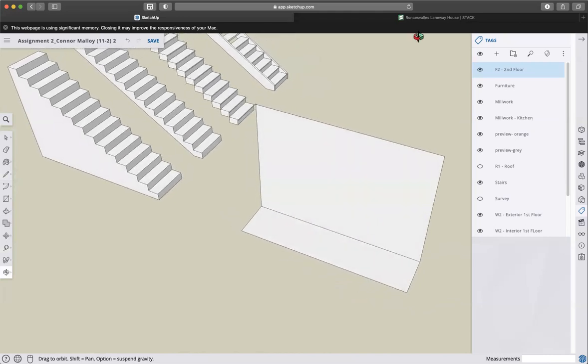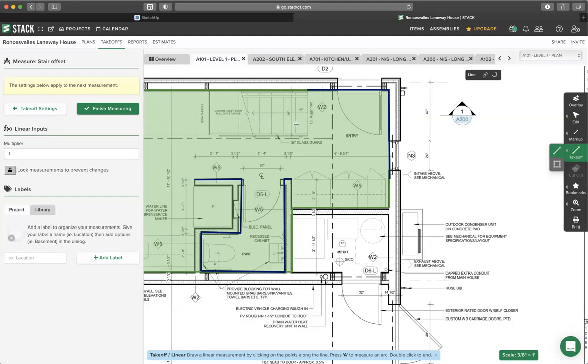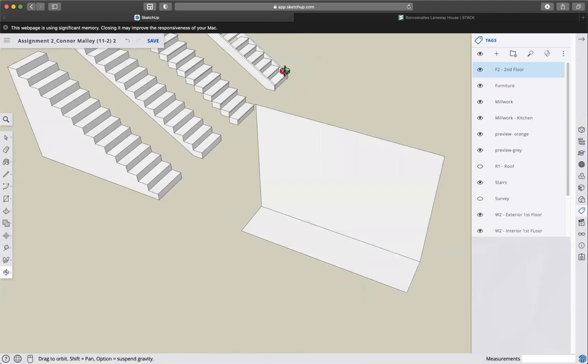Now, the other thing we know from our stack file is that this stair has 15 risers, and it says it's 7 1/4. That is the suggested height. When you work with a stair fabricator, they're going to do what we just did. They're going to measure from the top of the first floor to the top of the second floor, take that overall height and divide it by 15. They won't build a staircase of 15 risers by 7 1/4 because it might actually be a little bit short or a little bit high on that floor.